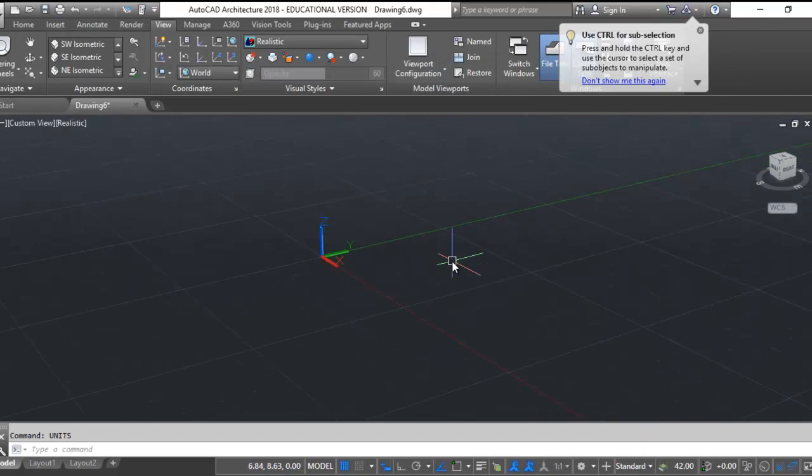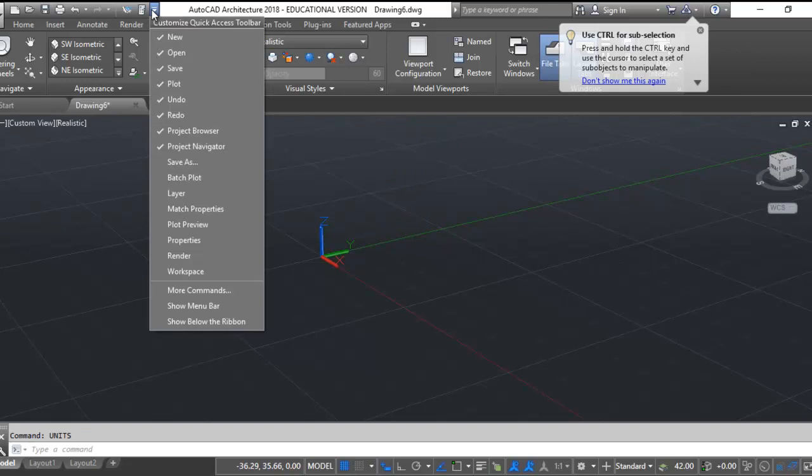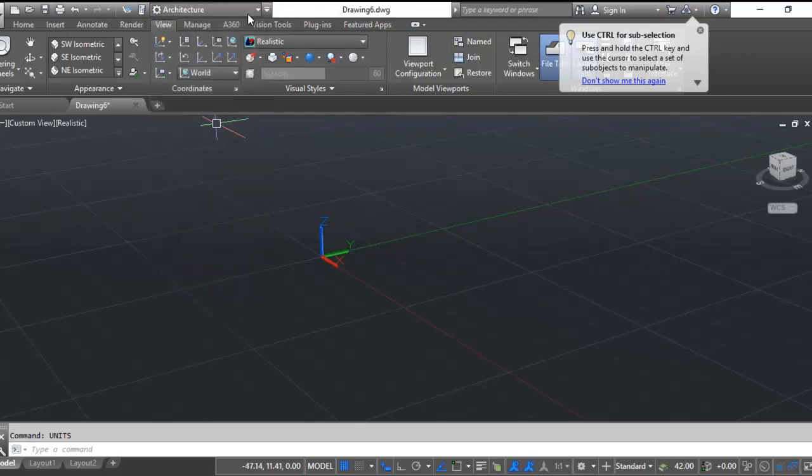So let's start by making, there's different ways we can do this. We'll do this with some base solid shapes. If you don't have your workspace turned on for the 3D, you can go in here, go to workspace, and then within the workspace menu, you might have different options here. In my case, I don't have the 3D right now, so if you have 3D, you can turn on your 3D modeling workspace to make this a little bit more user-friendly.